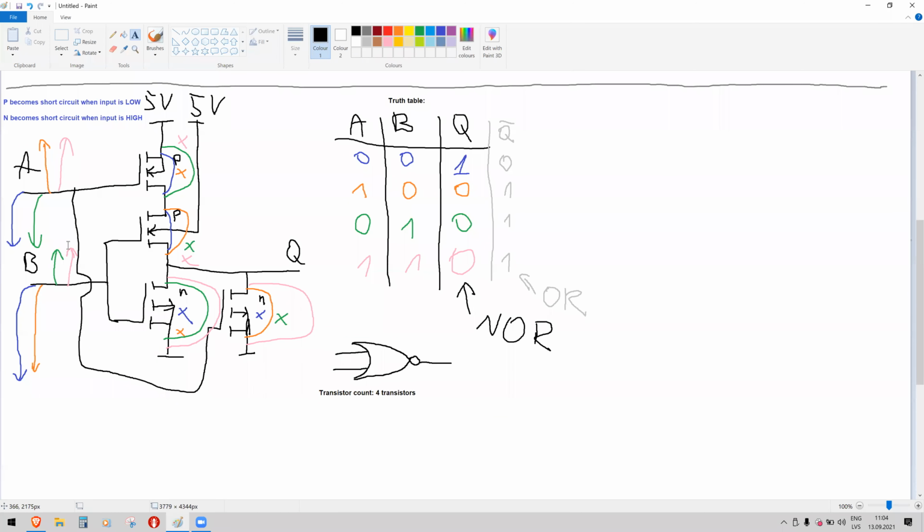Next question, what is the propagation delay of this circuit? How many taus do we need to wait until a change in the input propagates to the output? Somebody says 2 tau. Okay, but why? Let's say the inputs are changed at the same time. So let's say I change A low and B low at the same time.